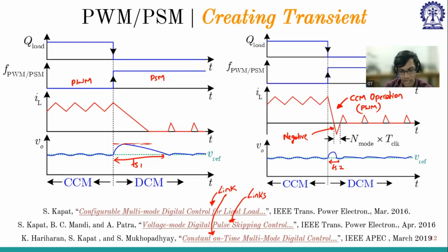Yes, but this is not the only condition that we'll see to decide the capacitor, because this is one such transient case study. We'll finalize the capacitor based on the worst-case situation. When there is a very high step up or step down transient, the voltage should be within certain limits, and for that to be achieved, what is the capacitor requirement? That decides our capacitor.